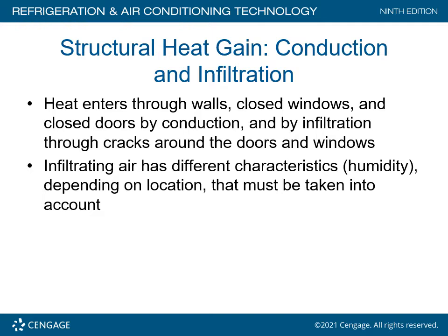Things like a ceiling on top of a ceiling, as an example, or penetrations through the ceiling, like for electrical boxes which are not properly sealed, show up. You'd be very surprised how much things like that will infiltrate and cause your heat load to rise inside a residence or a commercial building.